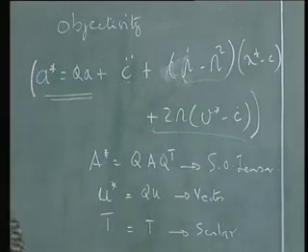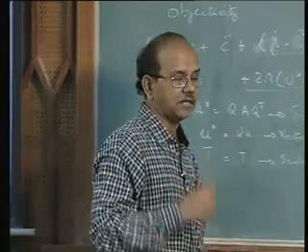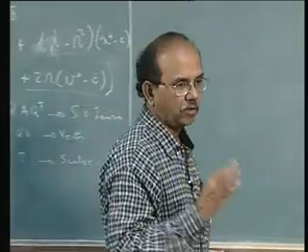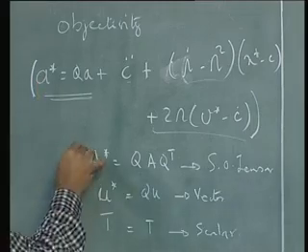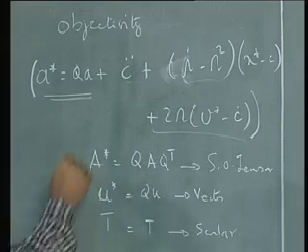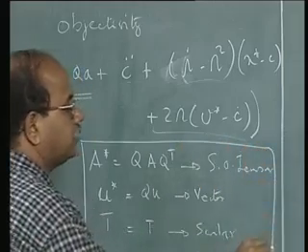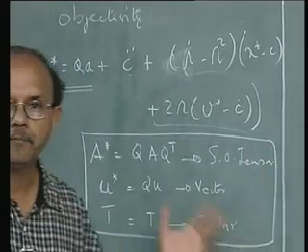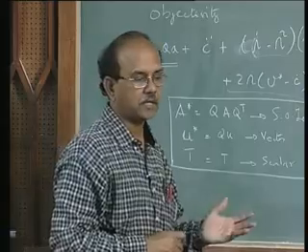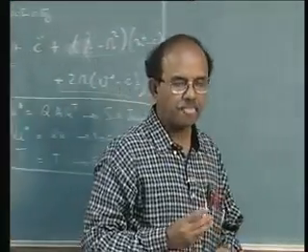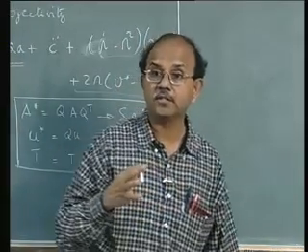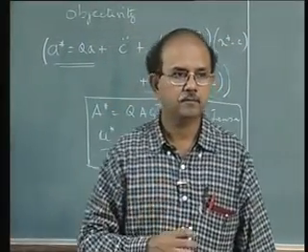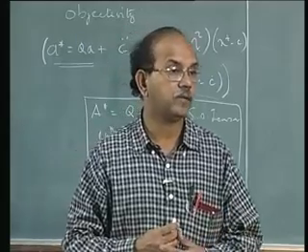We also recognize, for example, that if this part is 0, then we say that the transformations are Galilean, and there are what are called Galilean frame invariants. Let us not worry about that, but we will only worry about material frame indifference as it is applied to continuum mechanics. So let us just summarize with the fact that these are the types of changes that would take place between the starred and the unstarred coordinate system. Now let us look at certain quantities of interest to us and see whether these quantities can take part in the type of constitutive equation which we want to build.